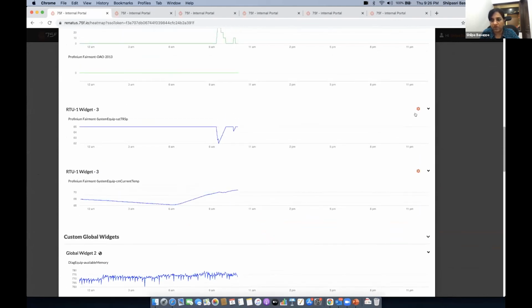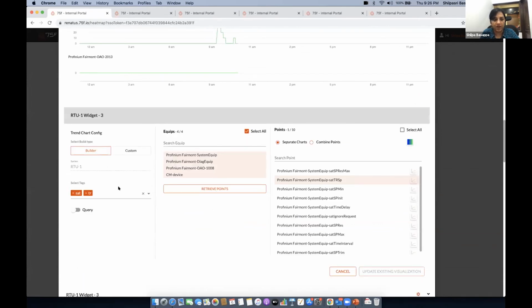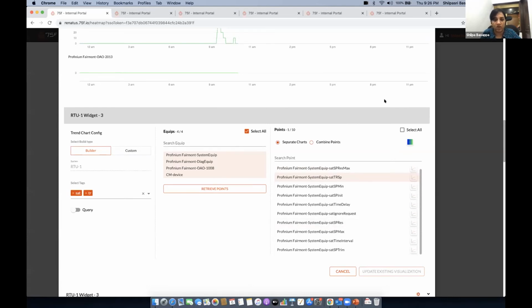one of the widgets which we can configure. So let's say I edit in a building. Currently, I'm trying to build, we have supplier temperature. We have used GPC 36 for the VAV profile. So we have trim and response logic that is running. And if there are parameters that we would want to monitor within this, we will be able to bring that up, plot it, and monitor that.